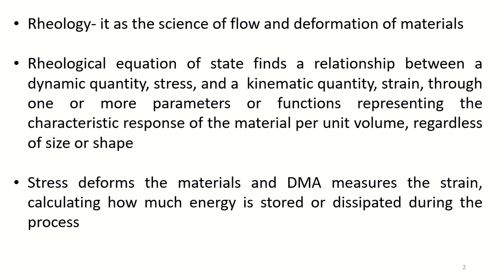Stress deforms the material and DMA measures the strain, calculating how much energy is stored and dissipated during the whole process. Although gels and some viscous samples can be tested, a DMA instrument is specially adapted to the rheological study of solid-state-like materials.